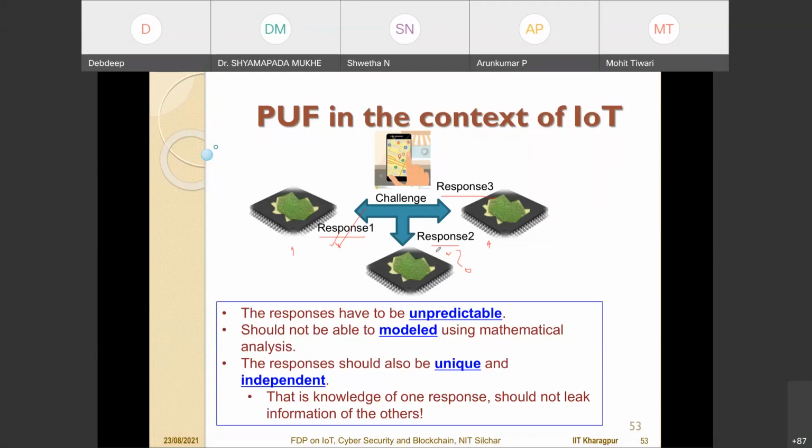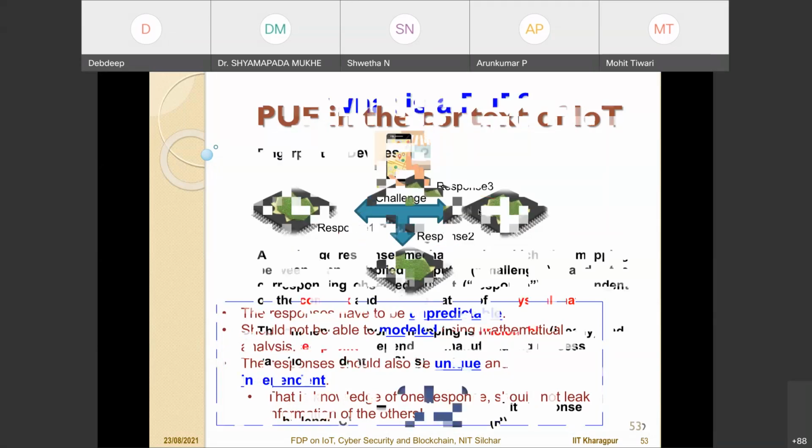Therefore, the PUF should be resistant against machine learning attacks, or model building attacks, because machine learning tools are very smart and getting smarter. If you give access to the inputs and outputs, and the machine learning tool is able to tell you the mathematical or physical model, then the entire security guarantee will collapse. The reason PUFs work, or should work, depends upon the underlying physics.